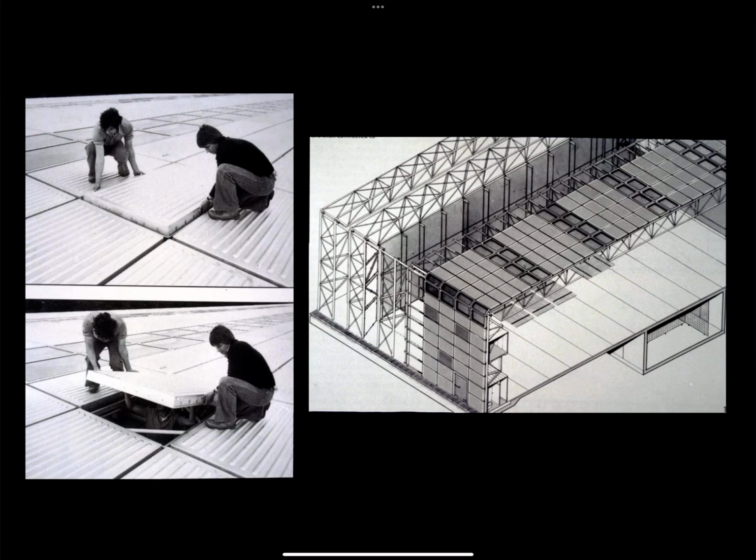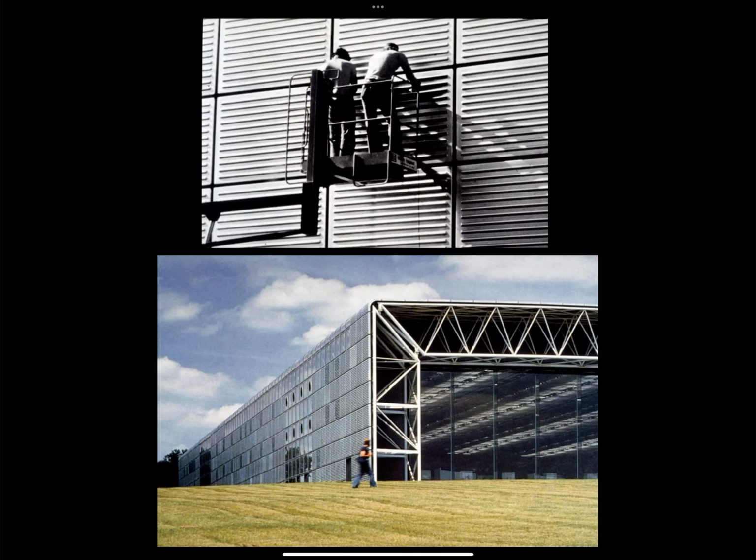So the materials here then are aluminum and rigid insulation. And you can see that the surface of the aluminum panels is profiled. It's a ribbed surface, and this is true both inside and out. This is done in a vacuum press with very thin aluminum, which is called superplastic aluminum. So that doesn't mean that it has plastic in it. It means it has a bit of copper in it so that it becomes much more malleable and can be easily vacuum formed.